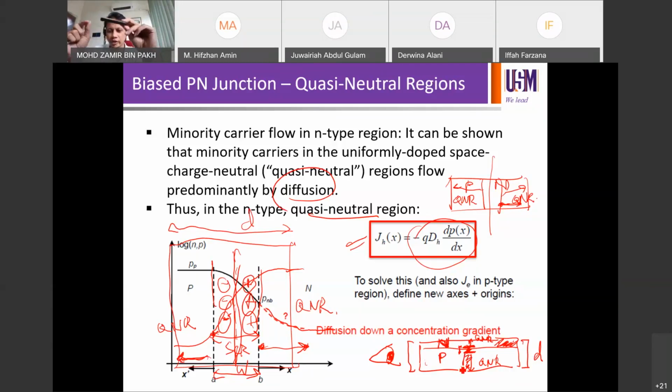So my depletion region is very, very, very small. This is just to relate to the concept that we're learning now, so that you know where exactly all this stuff is in the wafer. Now can you see what the wafer looks like, where the junction is, where the depletion region sits, where the QNR is, on this wafer? Can you translate all this sketch into this now? That's the most important thing.